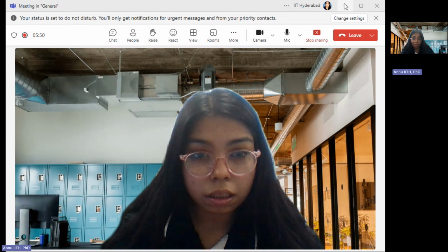So if you have problem statement 1 for this property: show that convolution in the time domain gives multiplication in the Z transform, and also discuss the ROC. The step-by-step solution is this. Rearranging the sums gives the product. And the ROC is nothing but the intersection of the individual ROCs. I hope you understand.